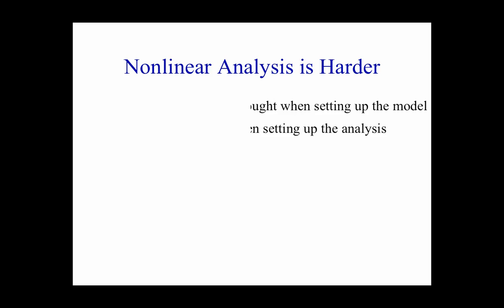Nonlinear analysis is much harder than linear analysis. It takes a great deal more thought when you're setting up your model, how to capture all the nonlinearities. Where are the problems going to occur? Are we worried about the beam to column connection? How do we model that connection properly? It's not just like putting in two elements. We really have to think about how we're going to do the modeling.